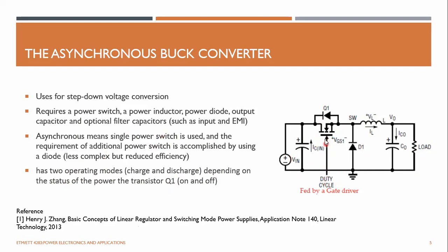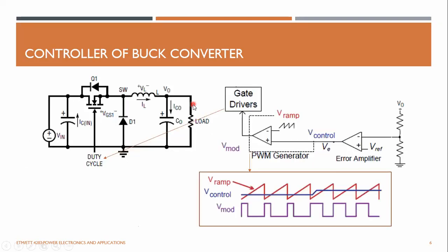The gate pulse of this switch is driven by a gate driver. You can't directly connect your Arduino or anything to switch this kind of power switch. So you always need to have a gate driver IC connected to this one to get the maximum performance. Right, so this comes with the gate driver. A gate driver is simply an IC like this.